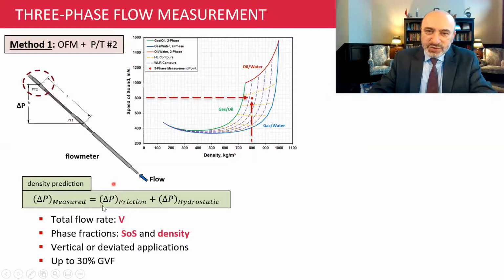Having a larger frictional loss means that the secondary PT gauge needs to be installed far away from the flow meter. How far will be determined on a case-by-case basis. For a given application, we will have to look at the data from the application and come up with the correct separation of the PT gauge number 2.